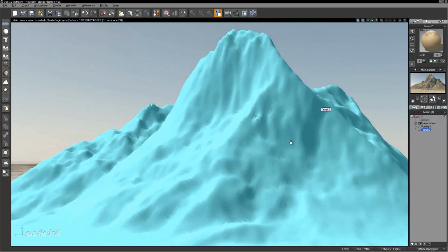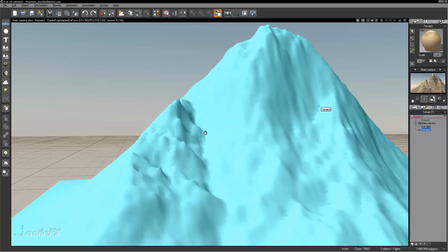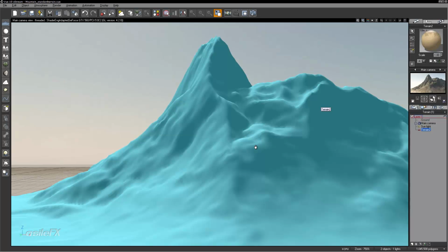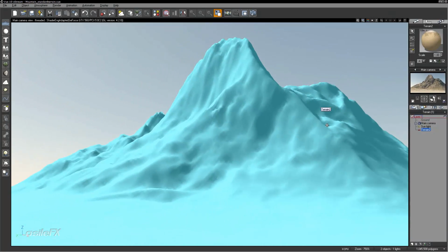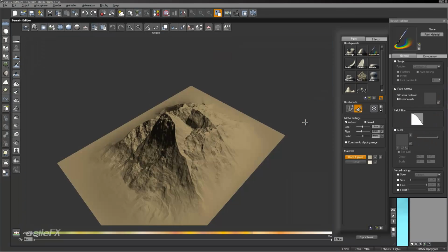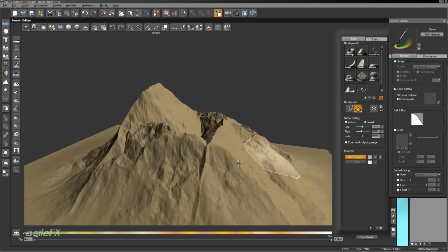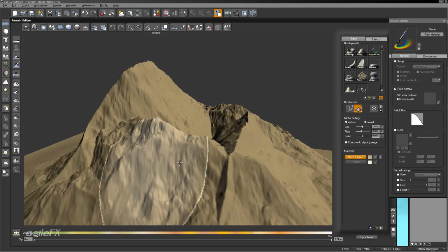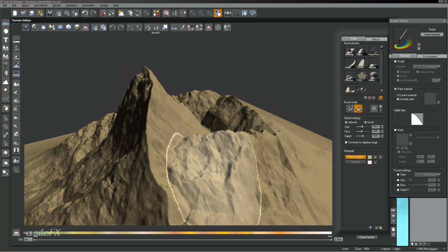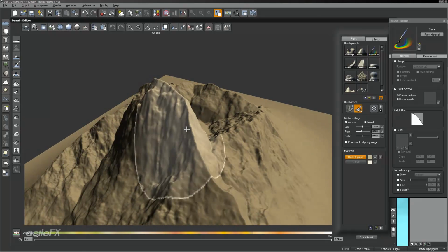So now we have this showing and covering up that default surface that's underneath. We could also remove the default surface and we wouldn't need an alpha. But if you did want to replace that later, it might be good to have. So now if we want to paint on this, we would actually need to subtract if we were to remove these areas and want to show the default. So with the paint material, we set it to invert.